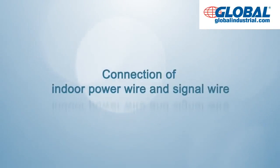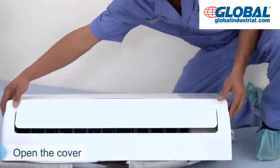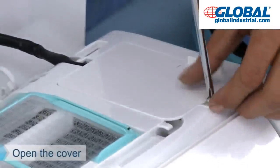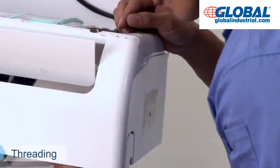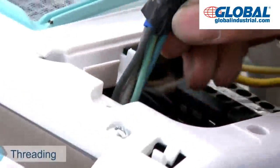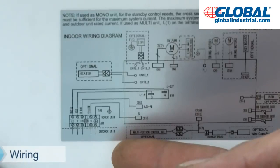Connection of indoor power wire and signal wire. Open indoor unit panel. Loosen the screw used for fixing cover of electric control box and remove the cover. Put the signal wire and power wire through wire outlet from the back. Connect the wires referring to wire diagram.